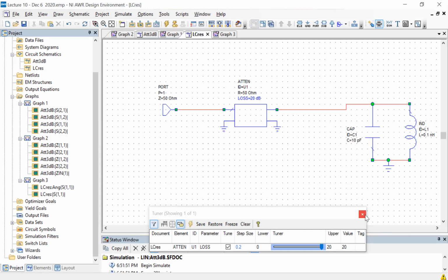Now, if such a filter is connected to your network analyzer with cables, those cables could have their own loss, right? They will have some loss, usually a few dB per meter or something like that. So what Jay was describing is that Sumeru must have taken those two cables, connected them together, measured the response of that, and used that as a reference. Either you just note that value, but usually it's a frequency dependent number, so you can't really do it by hand.